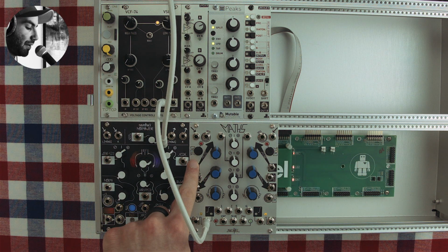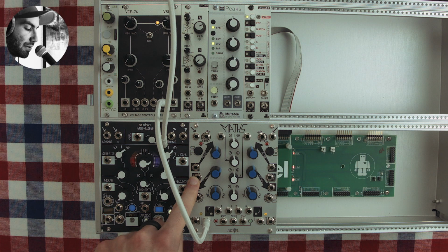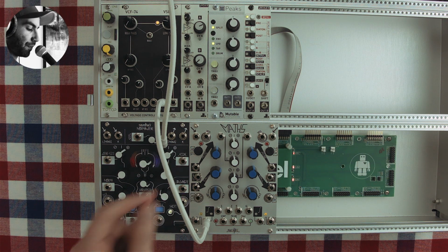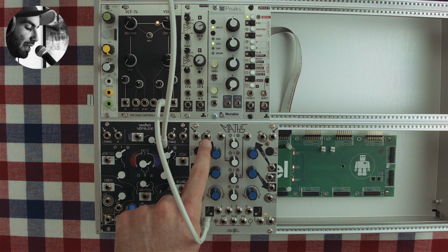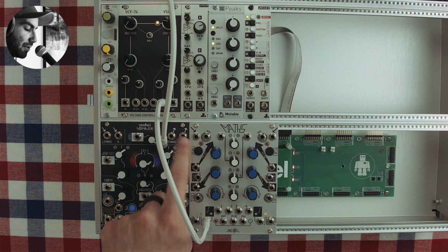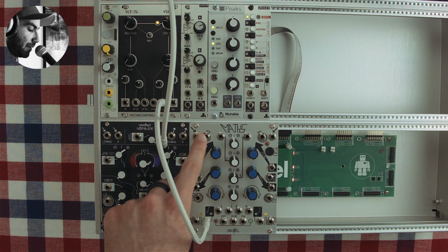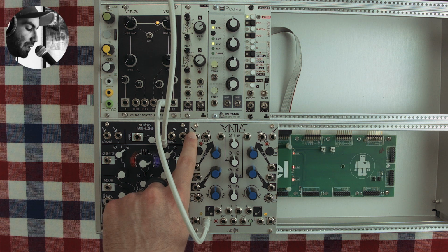Alright, so we've pretty much covered the rise, fall, and both controls as well as the cycle mode, which is the LFO. The other interesting thing we can try is the trigger and signal inputs here. So if I turn off cycle, the function will be controlled by the trigger or the signal here.